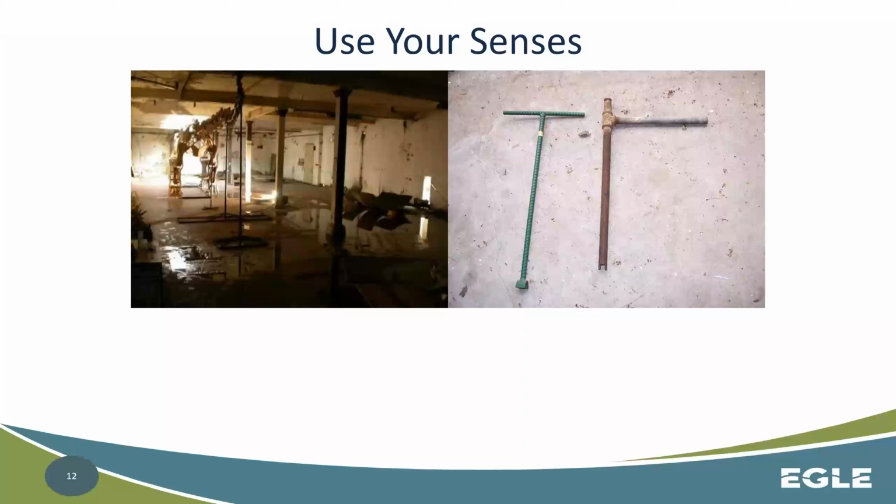You can do all kinds of stuff while you're there. You can be present. And being present is an active part of proper operation of a distribution system, right? If you're paying attention to what's going on, then you're going to be quicker to identify leaks, misuse, and other issues. If you are going to a house that's clearly occupied and every month you're getting very low to no readings off a meter, then that has to start becoming suspect.